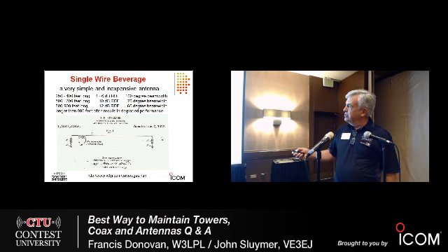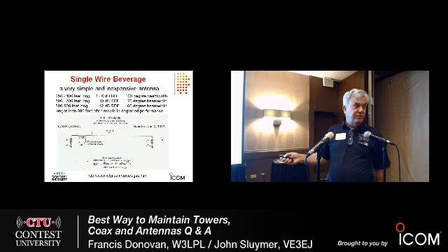A short Beverage on 160, it's got useful RDF. The very popular lengths around 500 feet or a little longer, about 10 dB. It's very good. And if you have room for something up to about 900 feet, really good RDF, about 12 dB. And I'll mention, there's a limit to how long you can make these antennas and have them consistently improve. If you make them longer than about 900 feet long, the performance is often degraded.